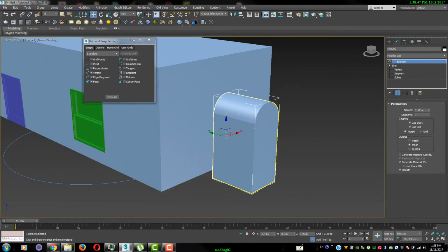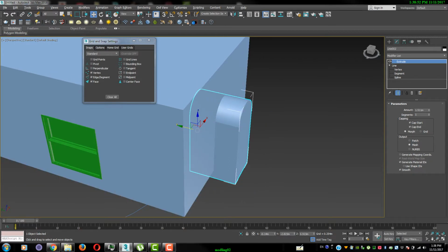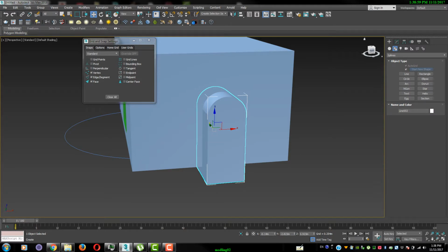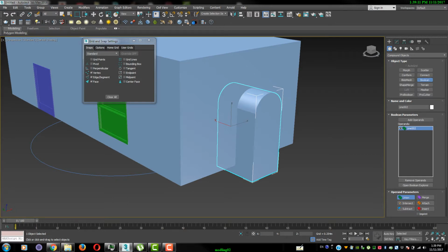So now I can move this object back. The second or third level of control for my object. Any geometry, there's a link between two geometries together. So combined object, I have here boolean. I can choose union, intersection, merge, attach, insert. I want subtract. This is subtract.